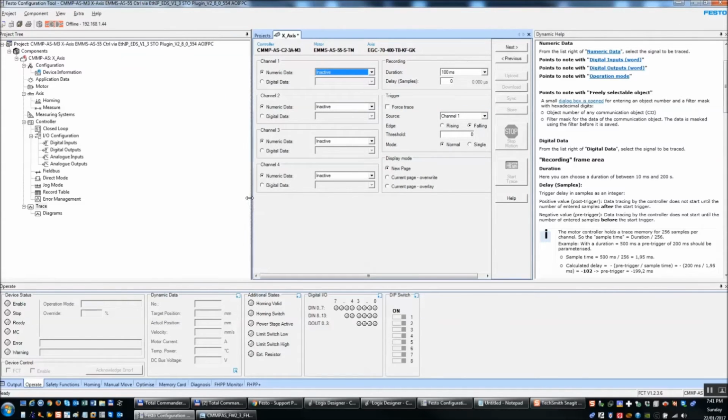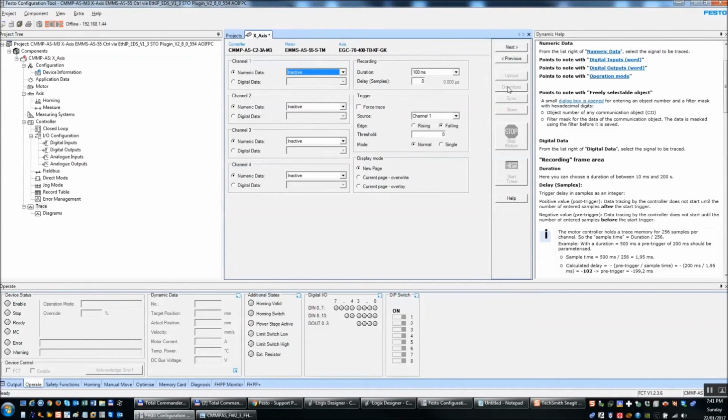The last thing I'd like to explain in here is that you've got a couple buttons over here. So if you go online and there's existing code and it doesn't offer you the pop-up to download or store or anything like that, the buttons over here, which are grayed out right now because I'm not online, these allow you to upload, download, sync, and store. So what are these buttons? Upload. So the controller has a project. You want that project to be here. You say upload and follow the directions. Download is where you take this project file we just did, download it.